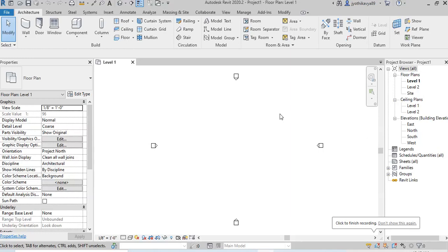Now let us understand the user interface of the default page here, right? So you can see all these frequently used tools are arranged here. This is the quick access toolbar, right? You have options for saving, opening, printing, dimension lines, room tags, texts, 3D models, sections, pen thickness, windows, etc. This is called the quick access toolbar.